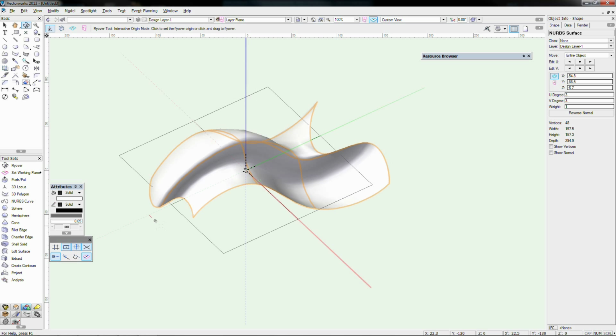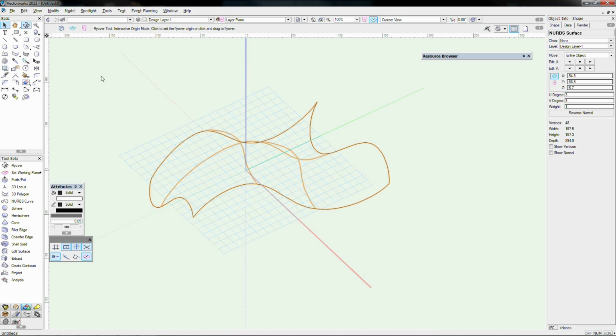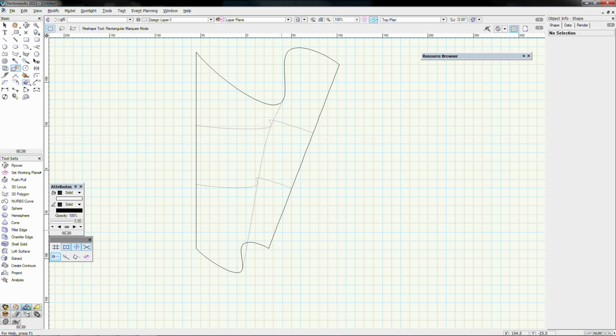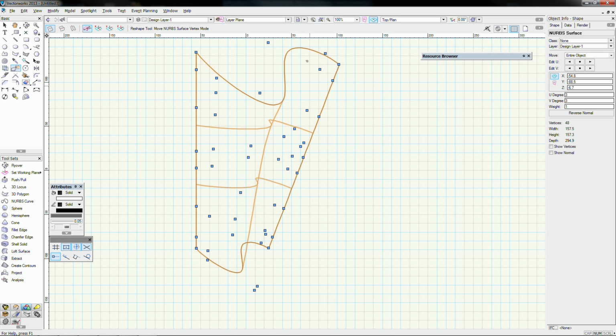Now also what that's done for us here, with all of these in fact, if I go back to a wireframe view, I should be able to double click on here and I get all these mesh points. Now this looks chaotic, and it really pretty much is. But if you look at this in a top plan view, or I'm going to hit the top plan view and double click on it here, the points are actually quite logical. So you've got endpoints, and then you've got divisional curve points that flow through here.